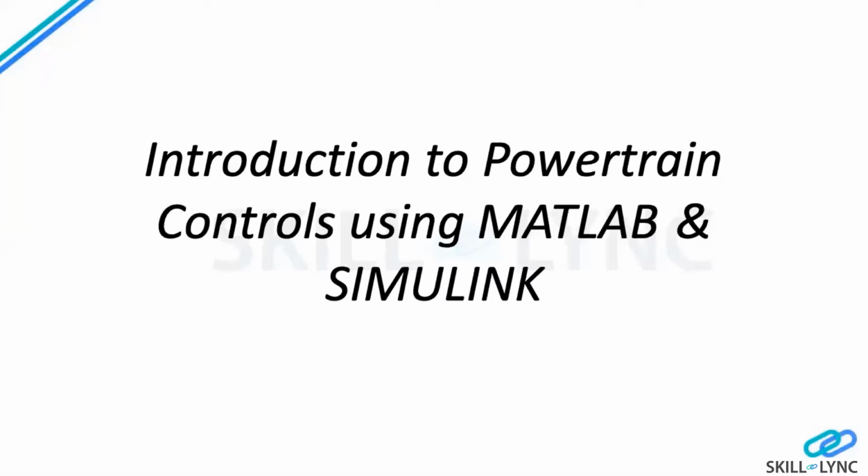Simulink is one of the main platforms that is being used to do the powertrain controls. The main control logic is built using Simulink, and there are a lot of coders like TargetLink, etc., which are being used to convert these Simulink models into code which will be directly used in the ECM.